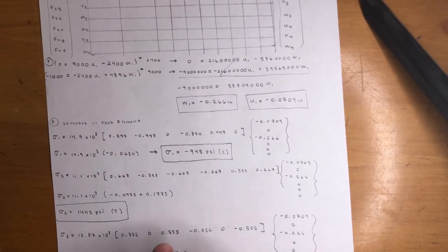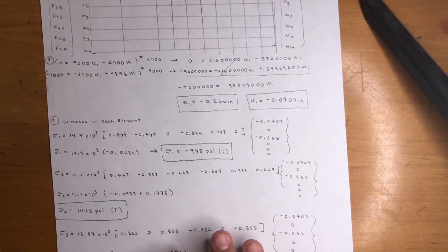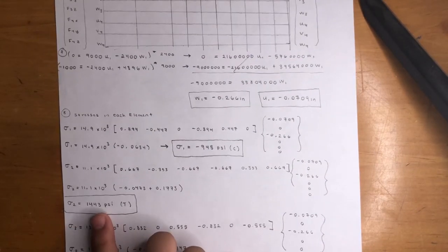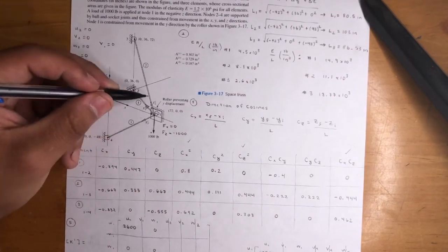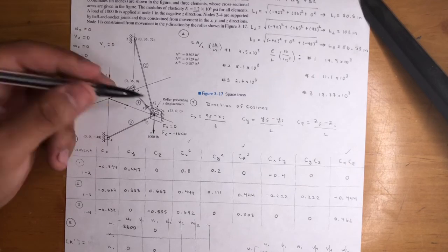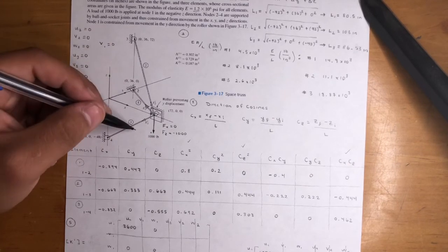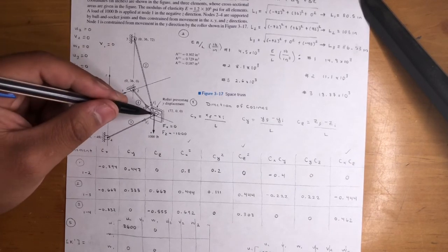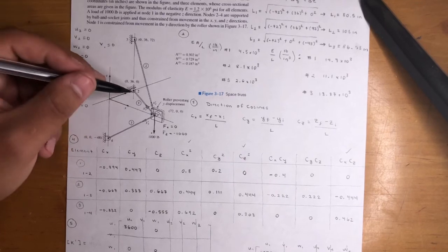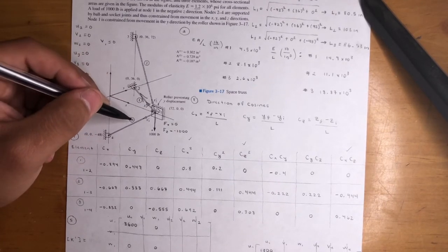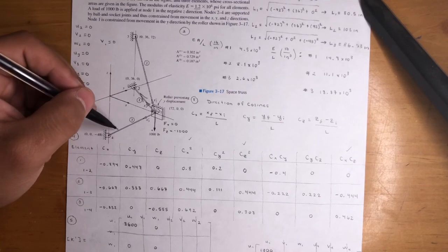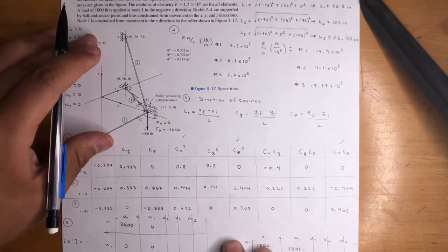But you could kind of verify these stresses. Sometimes, in this case, let's go ahead and see. It's saying sigma 2 is in tension, so it means element 2 is in tension. And yeah, it makes sense. If you're pulling it down, that means you're stretching this one. So that makes sense. You really can't see how these two are in compression. Well, you kind of can, right? If you got negative displacements, that means you're pushing into this node, right? Going into node 2. Into node 4, I really don't see it, but trust your gut, you'll be all right.